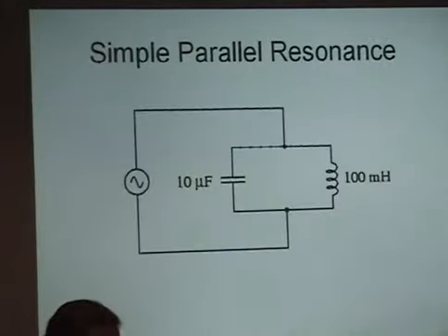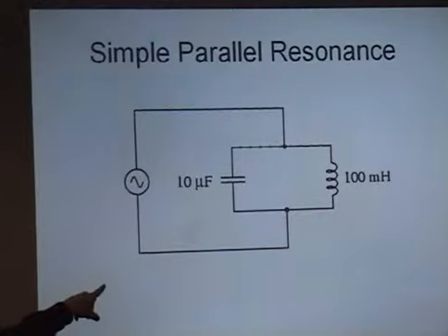So there I've repeated the equations again. Inductive reactance, capacitive reactance. Setting them equal, we get this. We simplify and we get our square root sign. And then we start working out. There's your 100 millihenry at 159.155 hertz, and you work out to 100 ohms. Many times when you want to create a tank circuit in your radio, you want to have 100 ohms be the reactance. It's just kind of a rule of thumb when you're designing a circuit.